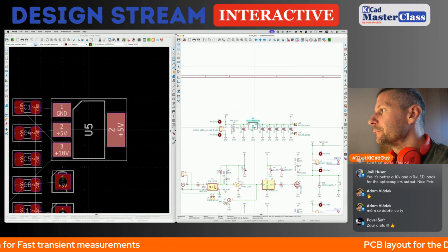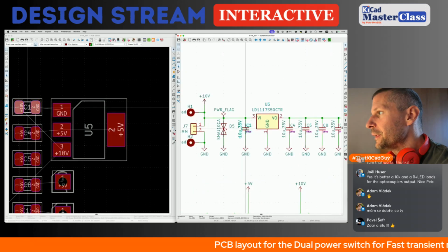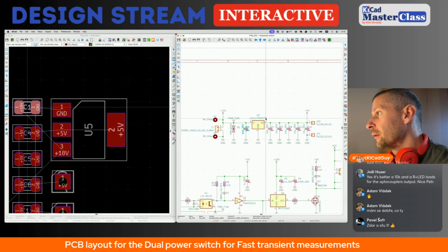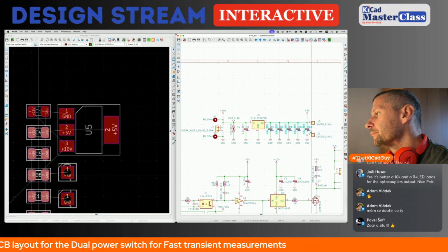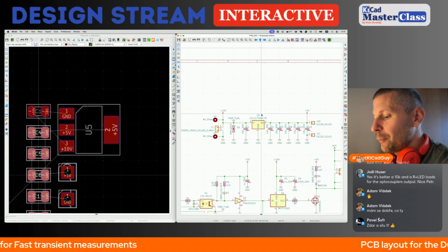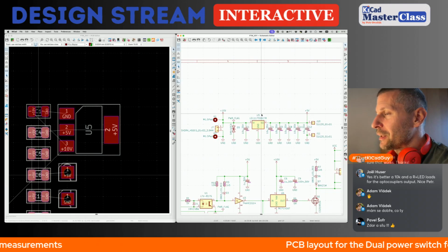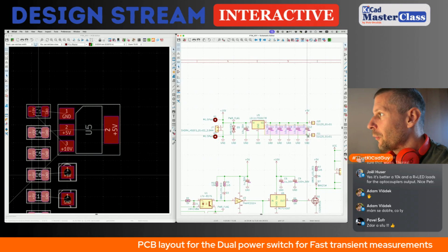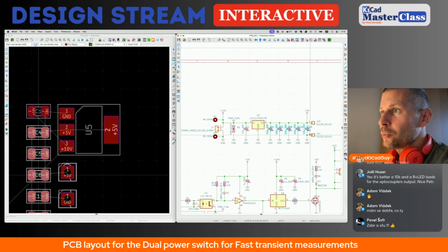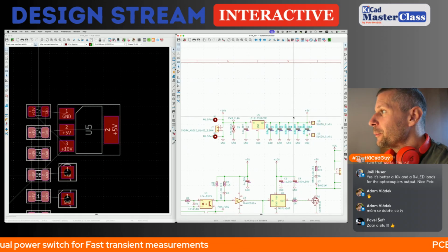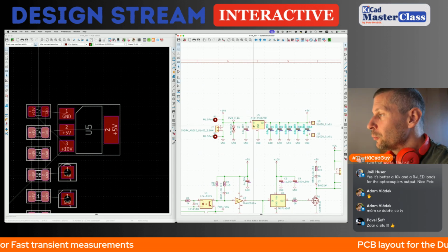The LDO with one input decoupling capacitor, and the battery of capacitors at the output. I checked last time that the maximal capacitance is not mentioned in the datasheet, but 50 microfarads is not too high a capacitance to be placed at the output of the LDO.